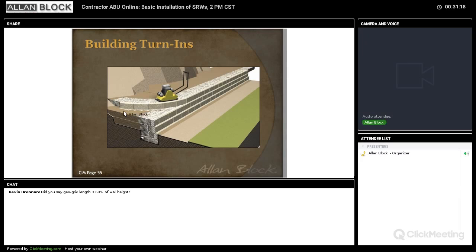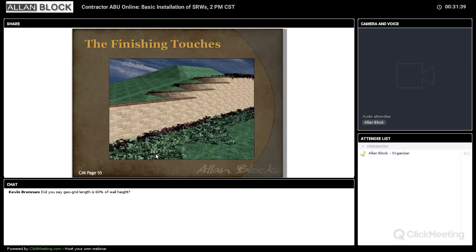You're going to put another gravel leveling pad, but below that leveling pad, you need to make sure all of that soil is very well compacted, or you could get settlement in this part of the wall, which would eventually look very bad. So over compact. Stress the idea of this area has to be very, very well compacted.